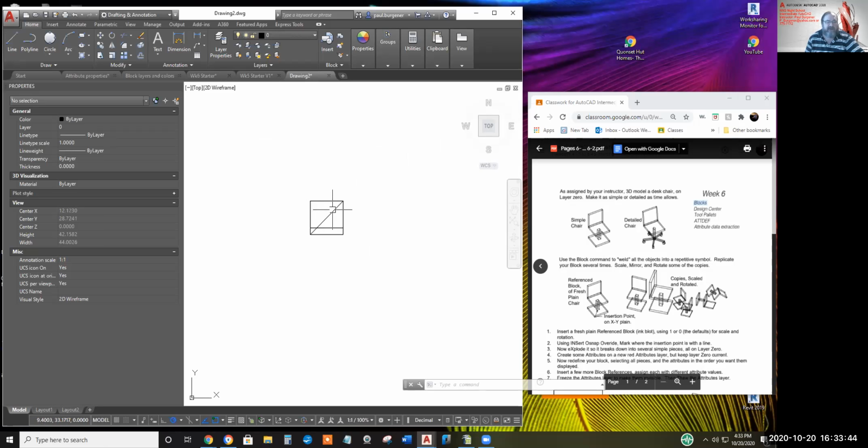Everything so far is on the 0 layer, and most blocks you'll see professionally made, I believe, originate on the 0 layer, because starting your objects on a layer other than 0 complicates the way they behave. And some expert might take advantage of the complexity, but I'd suggest let's keep stuff on 0, and we can rubber stamp it on furniture, chairs, electrical, or whatever layer we want. But anyway, everything's on layer 0.